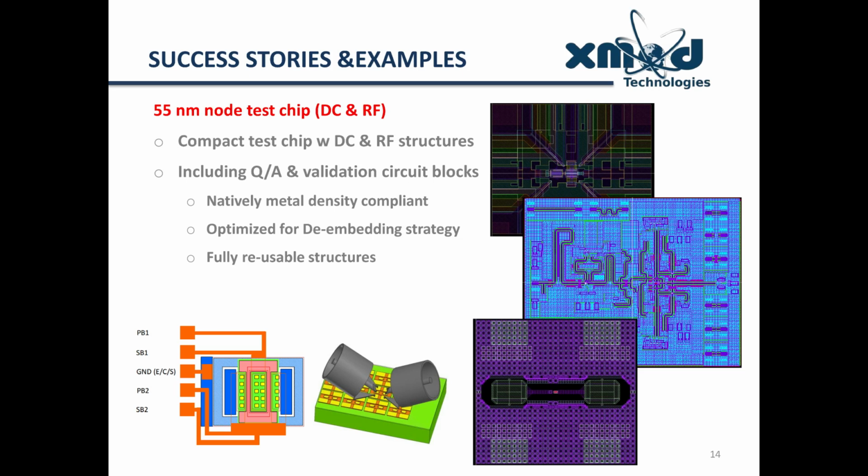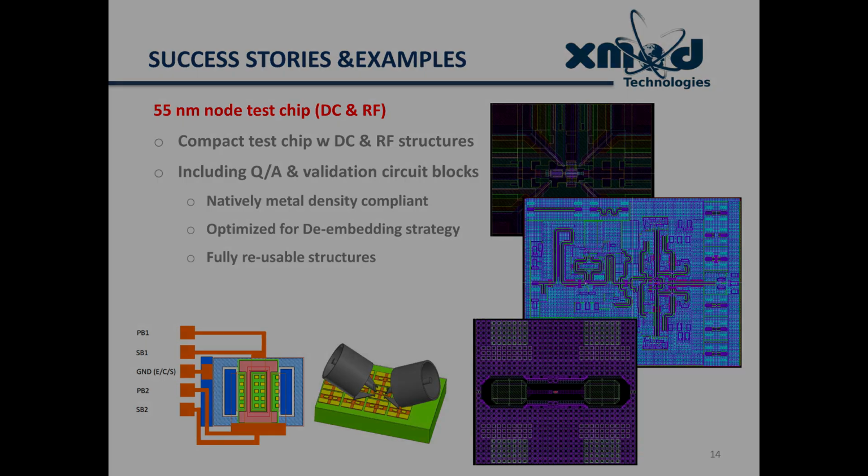Those are optimized for the de-embedding strategy. That means the de-embedding strategy has been thought well before the design of the test keys, and both are perfectly tightly integrated onto the test chips. And finally, those are fully reusable structures.